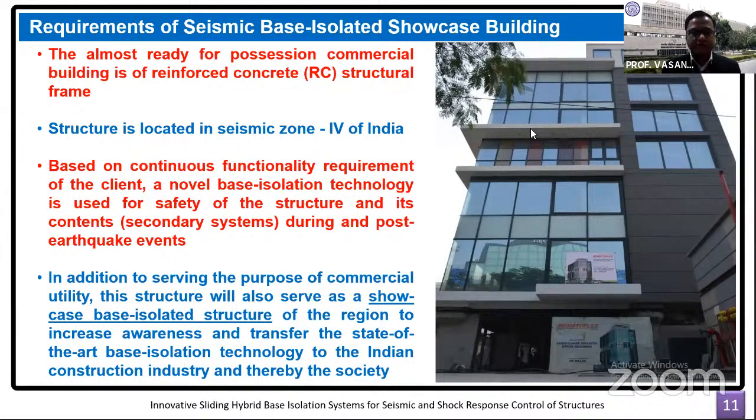Now, this objective was also important while deciding the location of the isolation system. As you have seen in the previous animation, we could have put the isolators either at the basement floor, below the ground, or at the ground level. But because it is a showcase building, we decided to put the isolators at a level that the visitors can easily see. So that decision went in particularly for this building.